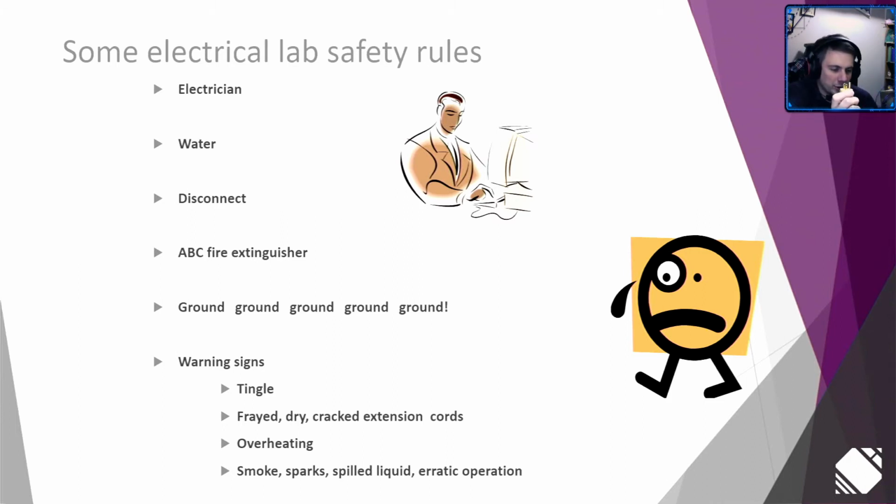But what some electricians do, and these are not the ones who would work at a mine site because they'll be fired immediately, they'll actually cut the ground off. That way the GFCI doesn't trigger and they don't get their work interrupted. It's a very unsafe practice because you're bypassing your safety system.